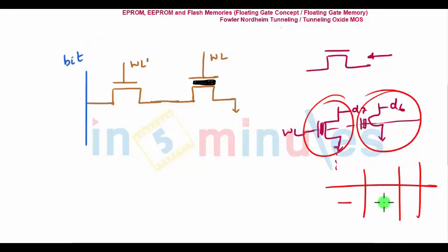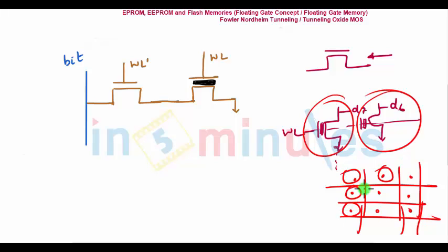If you are still confused, it is very simple. Suppose it's a cell of an array. All the cells, each location, would have had only one transistor, correct? Only one. Here, in case of EEPROM, you will have two transistors. Let's understand why. First, let's understand the two transistors. This is my floating gate transistor, correct? We have shown it with the input as word line. It's connected in series to a transistor which is called a select transistor, and we will quickly understand the use of this. And this is my bit line.